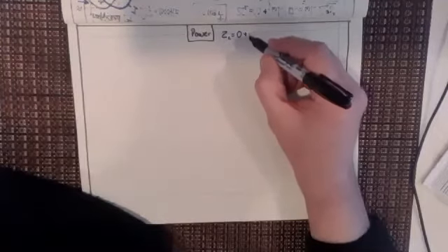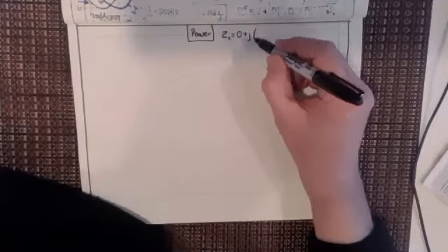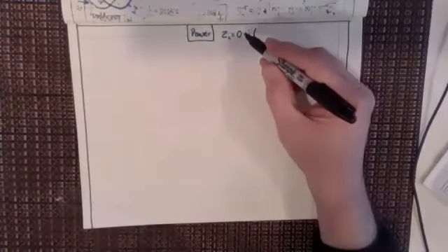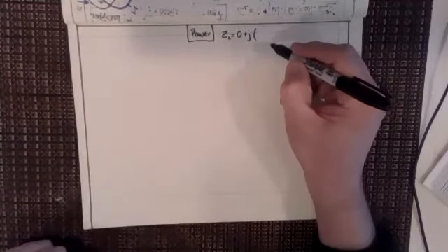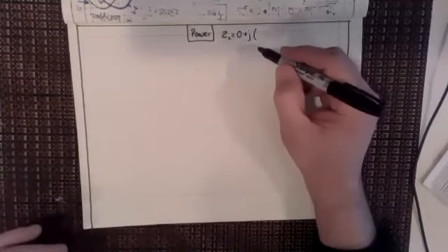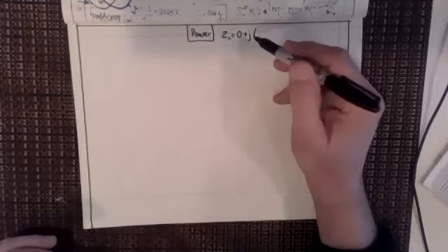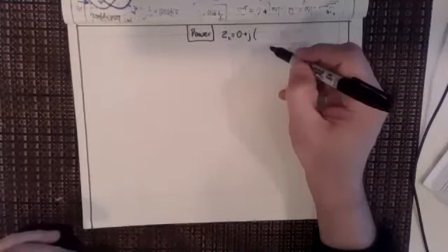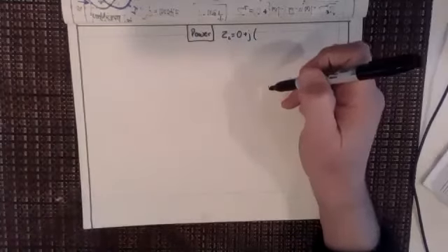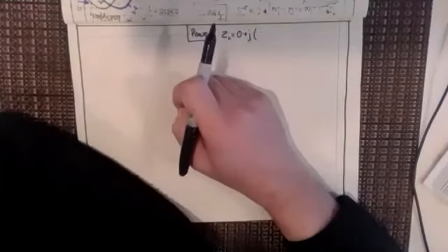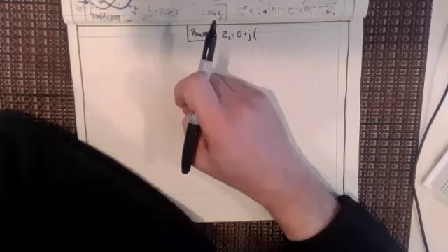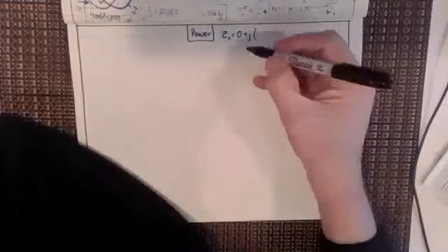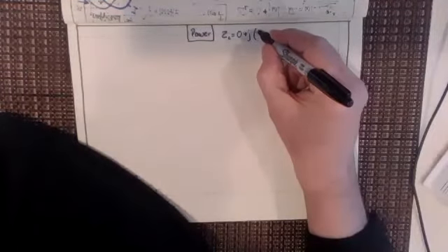So I'm going to put plus J. A lot of other professors teach it as 0 minus J 1 over omega C. Or a lot of them say that it's 0 plus 1 over J omega C. And you might think to yourself, oh my God, is 1 over J the same as minus J? Think about it. We'll look at that in just a second anyway. But yes, you can write it in a variety of different ways.